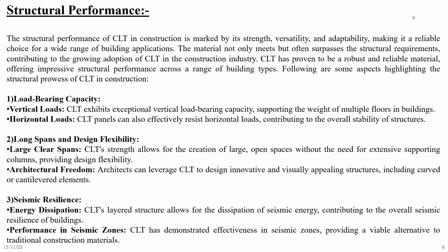Second, long spans and design flexibility. Large clear spans. Now, CLT strength allows for the creation of large open spaces without the need of extensive supporting columns, providing design flexibility. Architectural freedom. Architects can leverage CLT to design innovative and visually appealing structures, including curved or cantilevered elements.